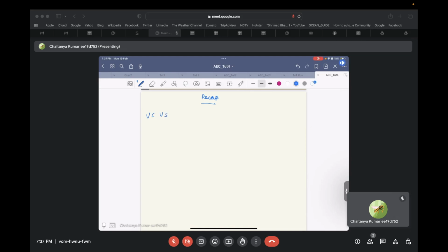For a voltage controlled voltage source, we need the input impedance, Z in, to be infinity. Why does it need to be infinity? Because it needs to sense the voltage at a particular node, and if something is to sense the voltage at a particular node, it should not draw current from that node, otherwise it will result in a voltage drop at that node.